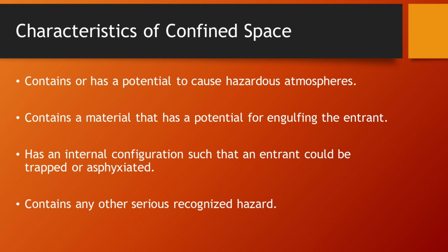Characteristics of a confined space: contains or has a potential to cause hazardous atmospheres. Contains a material that has a potential for engulfing the entrant. Has an internal configuration such that an entrant could be trapped or asphyxiated. Contains any other serious recognized hazard.